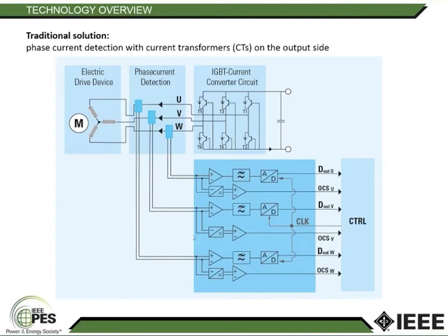So what you usually need is a gain amp, a low-pass filter to filter out interference, and some kind of AD conversion to get out a readable digital signal. If you have a second stage comparator in here, you're also able to get an overcurrent signal out. The AD conversion allows to also synchronize the 3 phases of the measurement that we see here. So synchronization can be realized through the AD conversion die that you use.